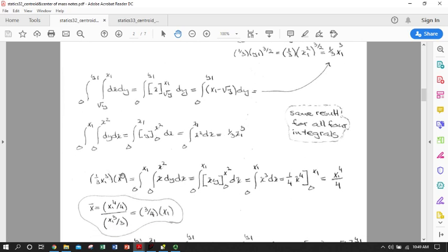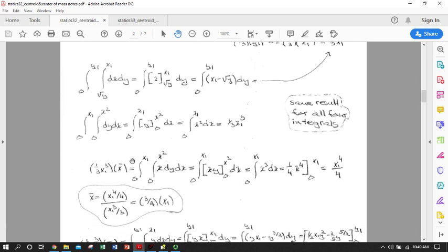So that was a bit of an exercise, just having fun with math. But getting down to centroid here. So now I'm going to use my double integral, my dA from the other page, and I'm going to evaluate effectively x dA using a double integral. So I have my x, and I'm going to integrate y from 0 to the function value for any y, which is x squared. And then I'm going to take that result and integrate over the relevant x limits, which is 0 to my x1.